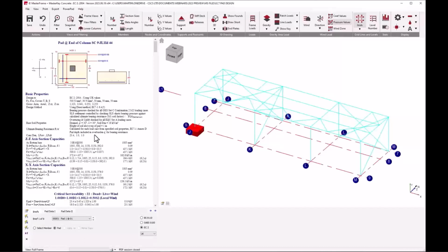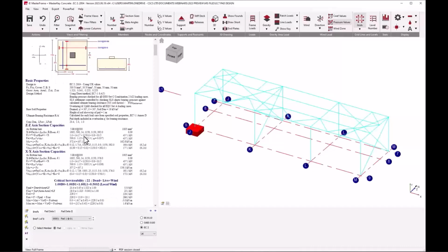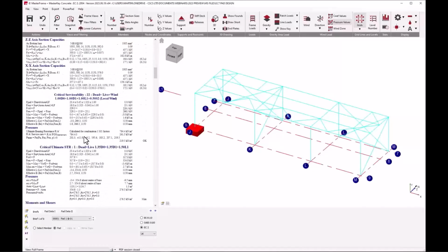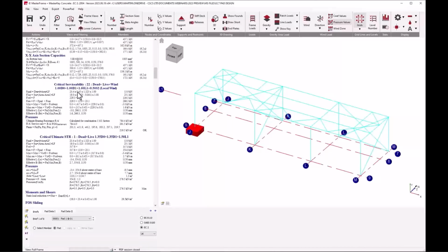we're saying the bearing resistance is calculated from Annex D, and you might expect to see some output on the screen at this moment in time showing you what the bearing resistance capacity is. However, that is very much a numerical thing that has to be calculated on a pad by pad, load case by load case basis, because the size of the pad that's under pressure and the direction of the shear force all come into play when calculating this bearing resistance. So you'll see the bearing resistance result for each individual load case, but not the detailed calculations because there are many, many of them.